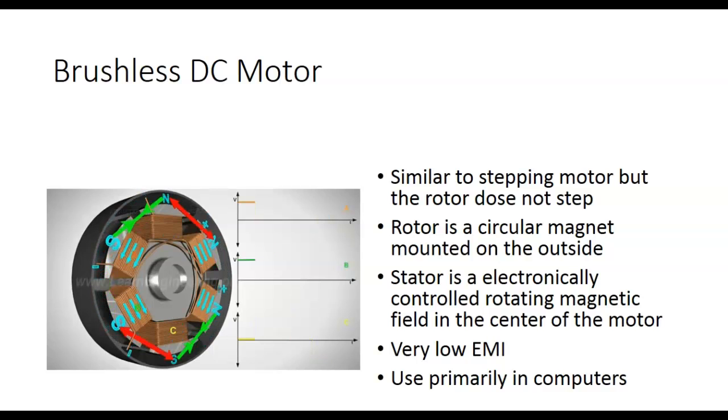Also, the problem we have, and this is why we had to go to resistive spark plug wires, guys, is that the first signals that they were able to transfer through the air was just generating sparks like lightning. We call them spark gap generators. So that's the way they were done. So the problem when these things arc is they put out tons of electromagnetic interference, EMI. And electronics and electromagnetic interference do not go well with each other.